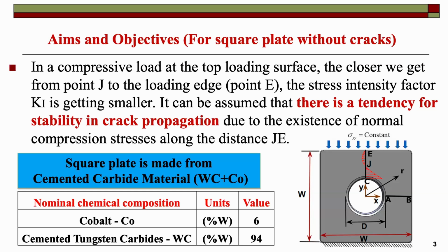And the stress intensity factor K1 may be smaller, because there is a tendency for stability in crack propagation due to the existence of compression stress along the line GE, the length GE of the plate.